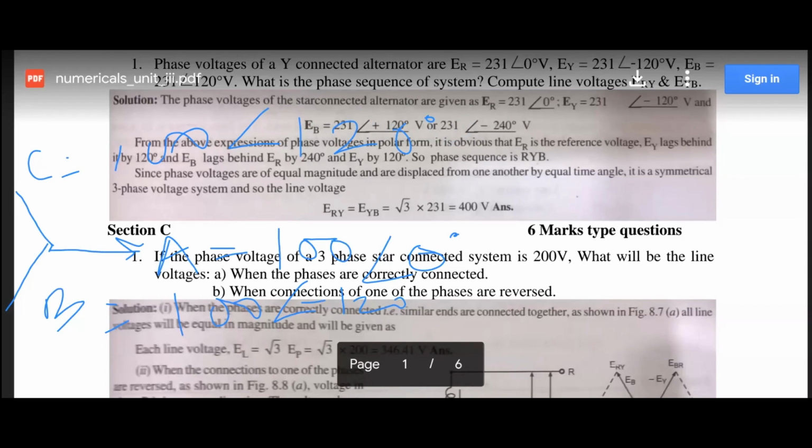Okay, because when we are following the positive direction of the x-axis, or the anti-clockwise direction as shown here, zero crossing will take place first by the A phasor, then by the B phasor, then by the C phasor.